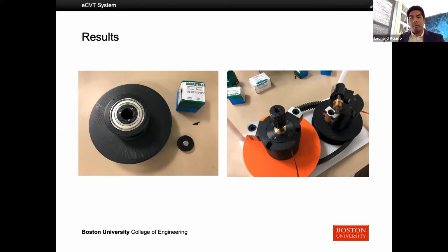In order to assemble the model, just as the actual device would be assembled, we utilized the intended screws, as you can see here, along with threaded heat set inserts, as shown here. Doing this allows us to simulate the manufacturability of the device, as well as making the device modular, disassembling it in order to replace any broken or outdated parts.